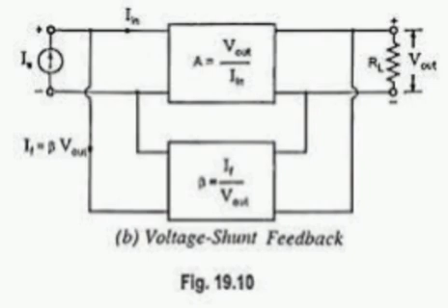Linear op-amp circuits. Inverting amplifier: Vi, R1, RF, V0. Gain AV equals V0 by Vi equals minus RF by R1, whole divided by 1 plus (RF by R1) by AOL. How can we realize minus RF by R1 whole by 1 plus RF by R1 by AOL?